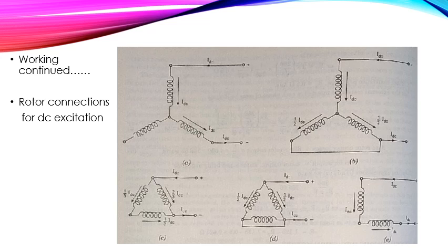So also in order that induced EMF in the field at starting may not be too high, the field turns provided are few in number and the excitation voltage is kept low. So as the exciter winding serves the purpose of damper winding, there is no need of providing separate damper winding with synchronous induction motor.